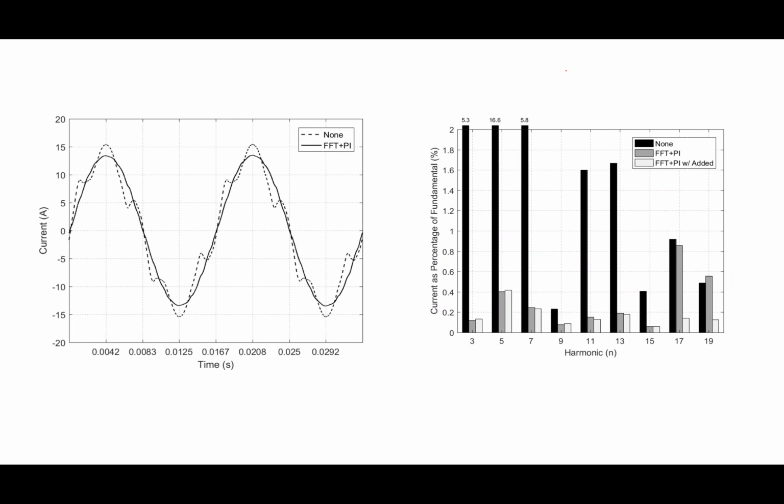We're going to learn how to compute the amplitudes of those sine waves. That's what Fourier series analysis is really all about. But I can have tools that look at a waveform and measure the amplitude at each of the frequencies. So in this case, at the third harmonic, so 3 times the fundamental, I have this much amplitude. At 5 times the fundamental, I have this much. And at the 9th, so 9 times the fundamental, it's a little bit smaller.